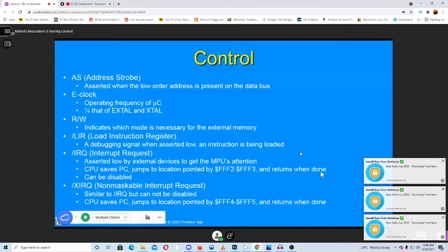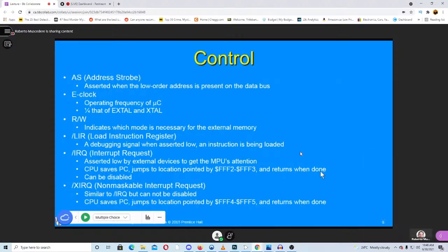So with interrupts, we do have the option to disable them. So we can actually tell the CPU that if an interrupt comes in, don't process it until I say you can, because I'm doing something really important right now. Okay, so this is a very useful thing, and we're going to use these quite a bit in our programming of this device.